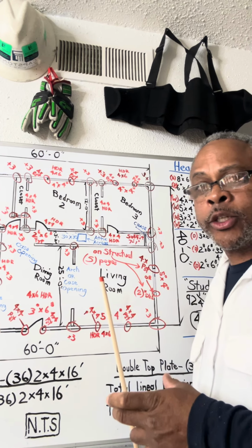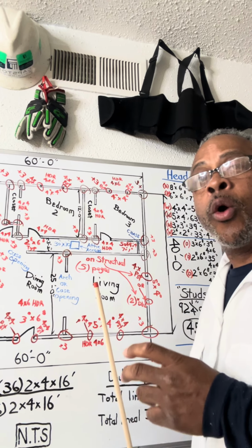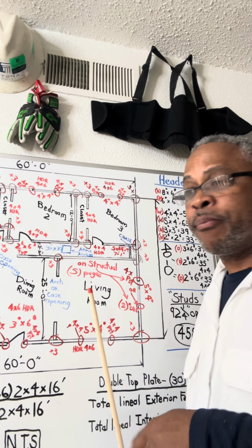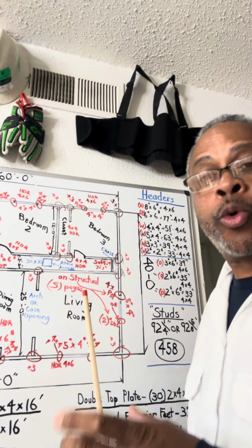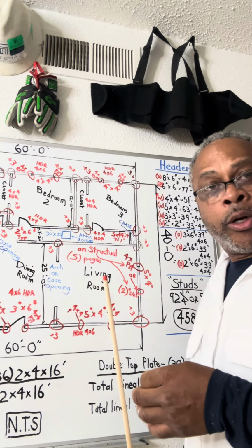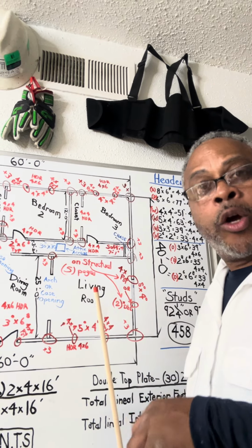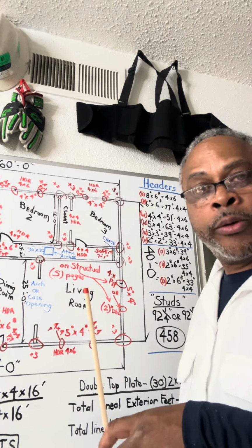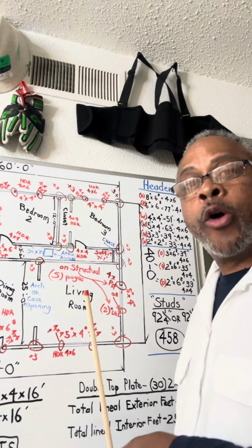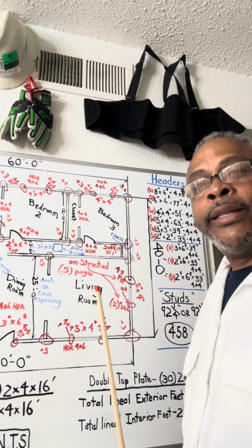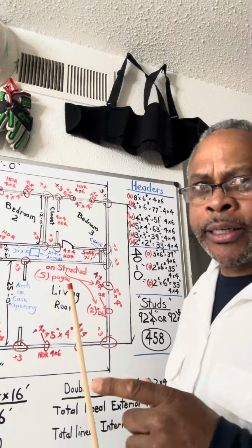There's no more round washers anymore. He puts a square washer, a 1/4 inch by 1/4 inch, that is measured for the square washer. It's going to have a hole in the middle of it. Then you're going to have a nut. More than likely, it's going to be a 5/8 nut, or it's going to be a 3/4 inch nut for a hold down. And the wall gets anchored down. Then you plumb the line with bracing. We're going to get into that as well.